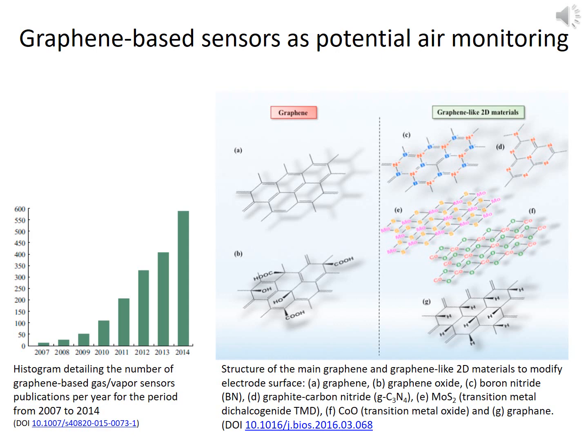One of the key limitations of sensitivity is fluctuations due to thermal motion of charges and other effects. Graphene sensors are capable of detecting individual events when a gas molecule attaches to the graphene surface. The adsorbed molecules change the carrier concentration in graphene one by one electron, which leads to changes in resistance. This sensitivity is achieved thanks to the fact that graphene is an electronically low-noise material, which makes it a promising candidate for gas sensors for hydrogen, water, carbon monoxide, ammonia, nitrogen dioxide, dichlorine, ethanol, iodine, and oxygen.